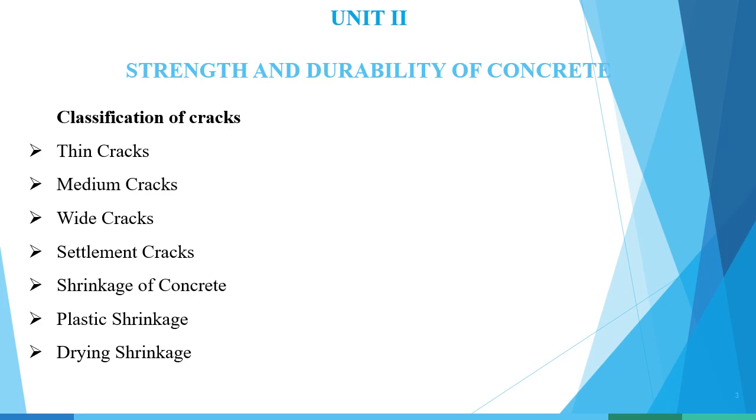Cracks can be avoided only if the stress induced by shrinkage strain, after relaxation by creep, is at all times less than the tensile strength of concrete.